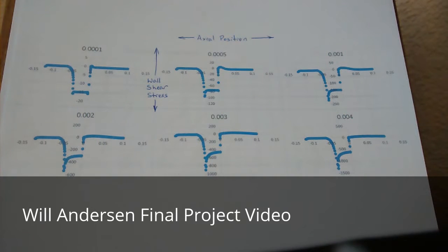The response surface, being a function, can easily be optimized using optimization software such as MATLAB. I started with an ANSYS model, which I ran at a series of different operating conditions to find optimal operating conditions, and took the data from those different sets of circumstances to create the so-called experimental data from which my response surface would be based. My two variables in my design space were x1, which was the mass flow rate, and x2, which was the axial position along the pipe. And then the function that was being evaluated was the wall shear stress.